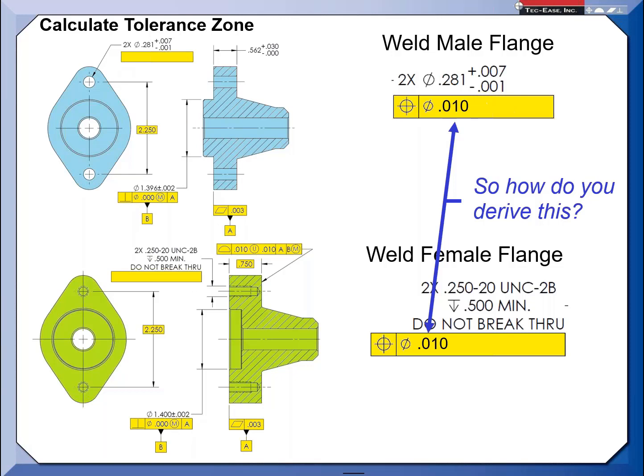We need to still meet design intent, but yet give manufacturing as much tolerance as possible to meet your design intent. So in this case here, there is a section in the standard, 14.5, called Appendix B, and we have formulas for positional tolerancing. So we have some defined rules, and if you utilize these formulas, you're going to find out that you can prove out mathematically where things can be and be compliant.